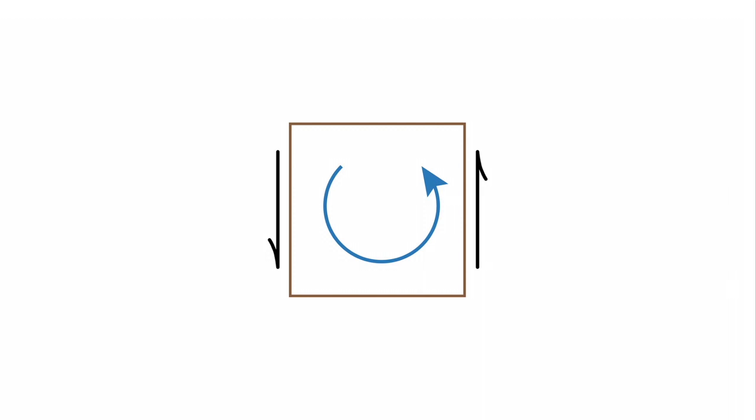But this is a static analysis, so if we have a tendency for the cube to move in one direction, we need to counteract it with an equal and opposite set of forces to keep that cube static. If we had a different set of shear stresses on these vertical faces, we would have a different sense of rotation in the cube.